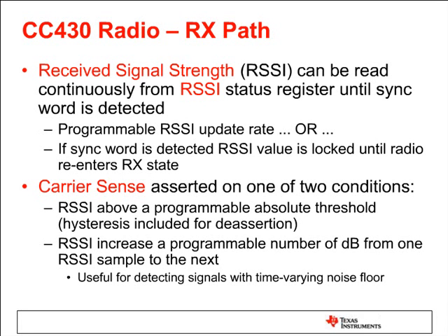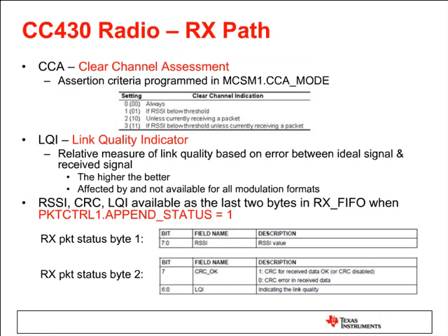But if no one's on the line, then I do move on to transmit mode. And all of these state changes within the radio happen without the CPU having to come in, check the RSSI, then send the transmit packet. It's all automatic, and it's definitely a power saver. So that's what is shown here in terms of clear channel assessment.